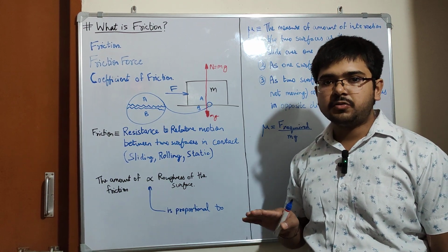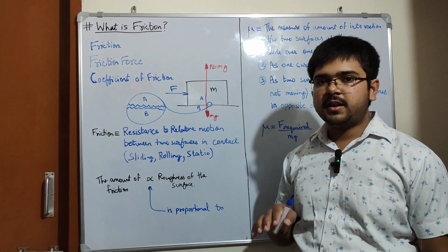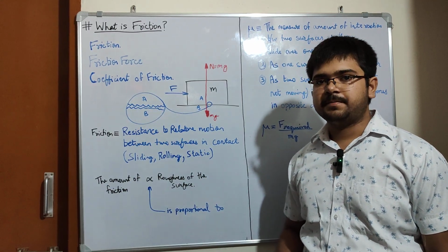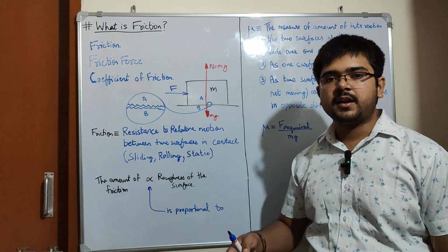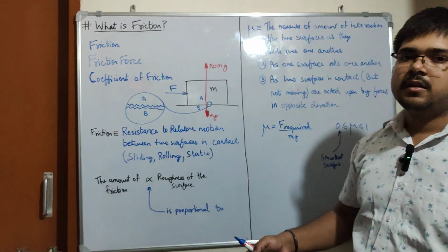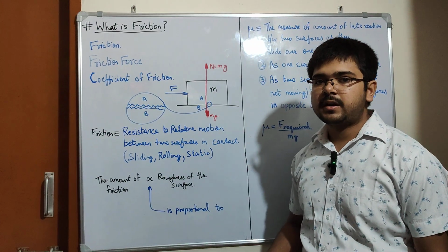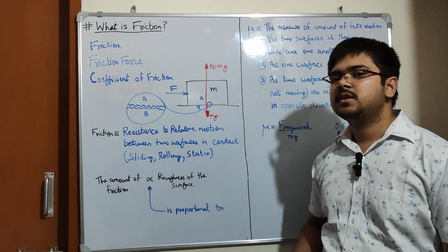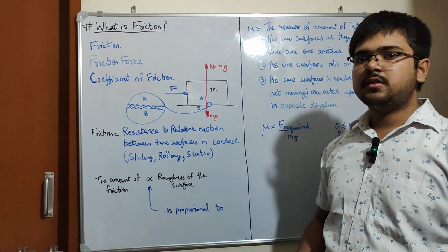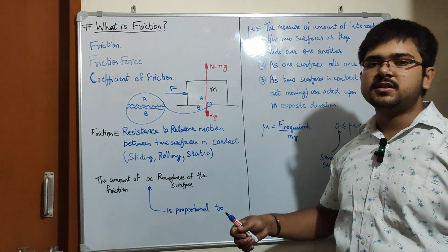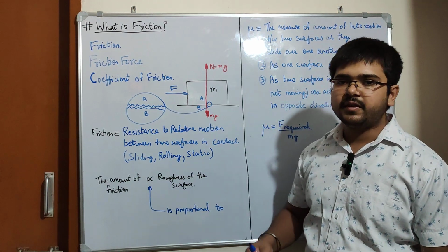But if the train is going uphill and it is also raining, then in that case we put sand over the rail, over the track, so that the coefficient of friction increases and the friction increases, so that the train can move upward.